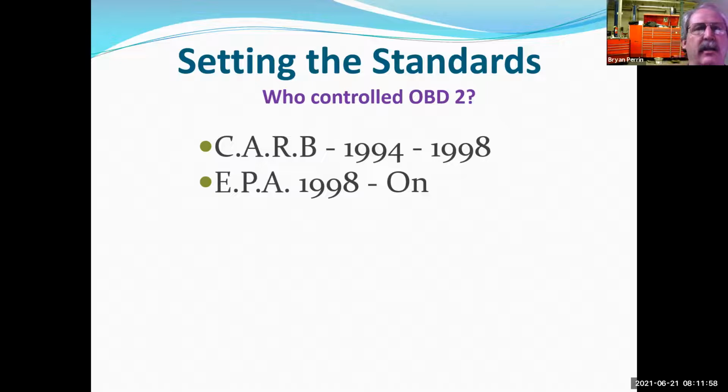Data that I can get on a 2020 vehicle might not be available on a 2010 vehicle or a 2014 vehicle or a 2008 vehicle or so on. So even though the framework that I'm going to look at is the same, my ability to get certain data or the requirement of manufacturers to set certain codes changes by year when those regulations came into effect, even though we call it all OBD2.